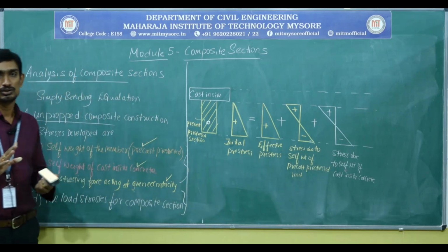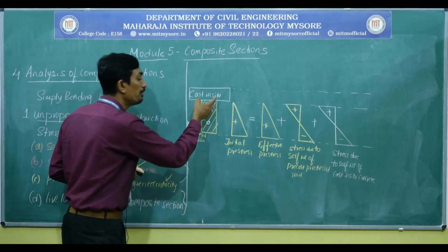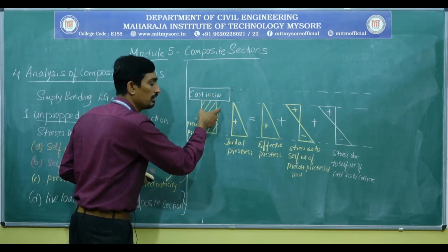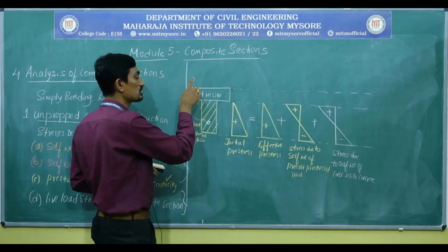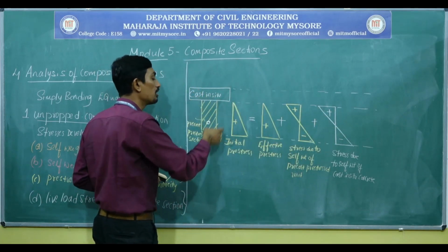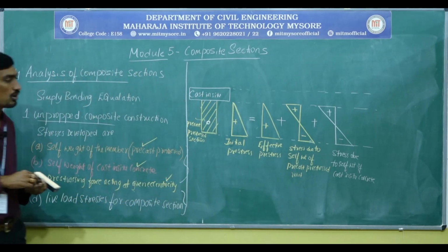Is it clear? Stresses due to the self-weight of the cast in situ are borne by the precast. So that's why I've written here: stresses due to the self-weight of cast in situ slab on precast. Next, we'll move on to the next.